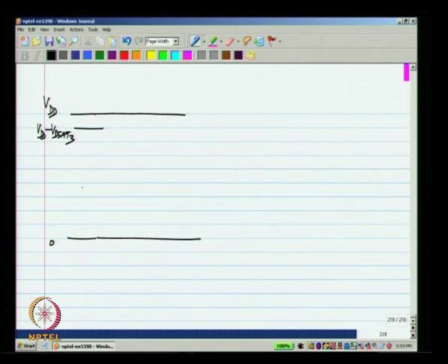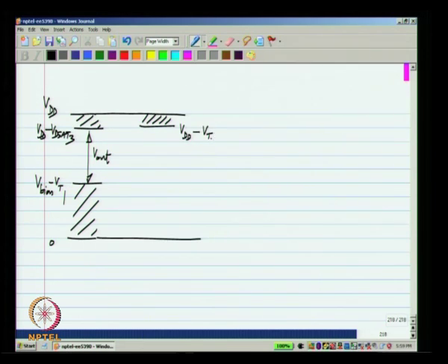And on the lower side it is limited by V bias. Okay. It has to be within this region, that is the range for V out, and V bias itself can go fairly close to VDD, that is VDD minus VT3 plus VT1 minus VD sat 3.